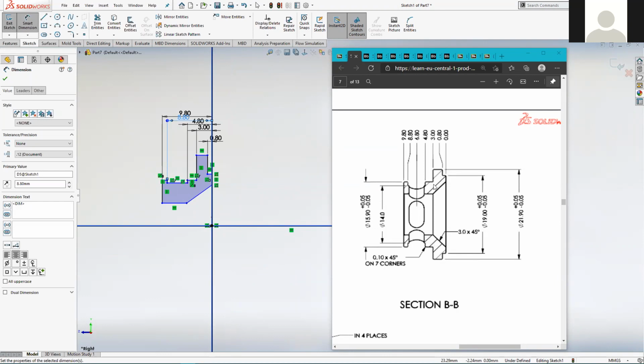So it starts off up here, rotates 360 degrees around the center axis, which means we should logically be drawing something down here as well. But that's not how you set a revolve up. You just draw the half profile, and then when you come to create the revolve feature, it rotates it around that center axis. So how do we put diameter dimensions on a sketch which is only the half profile?